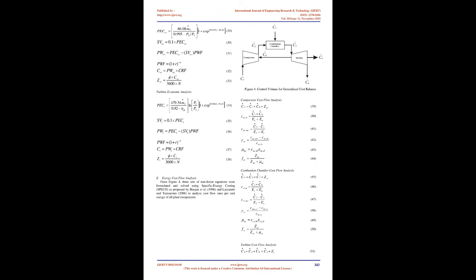B. Equations and analysis. The methodology employed consisted of simplifying the plant components into control volumes of energy and exergy flows and analyzing each flow based on the first law of thermodynamics and exergy principles. A typical plant component is shown in Figure 2, depicting energy and mass flow across the system boundary. Wherein are heat supplied, ideal work, enthalpy at inlet and enthalpy at outlet. The first law efficiency of the system component is thus given as Q_CV, W_CV, h_in, h_out. (3) Input energy, desired energy equals efficiency.